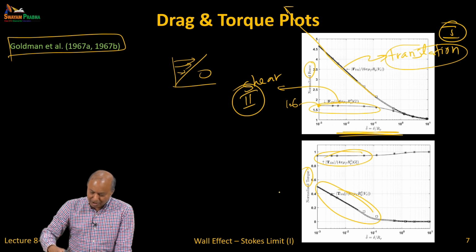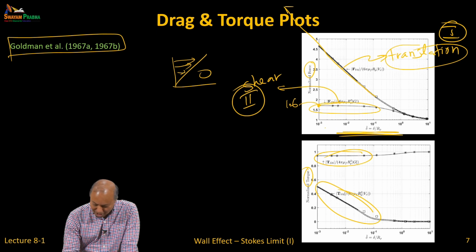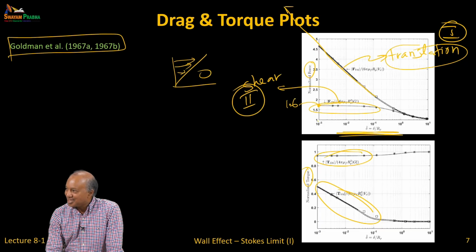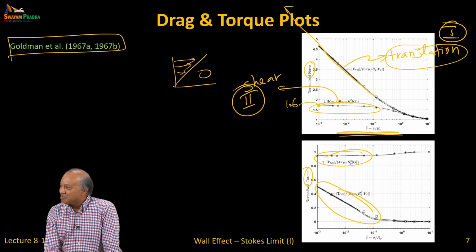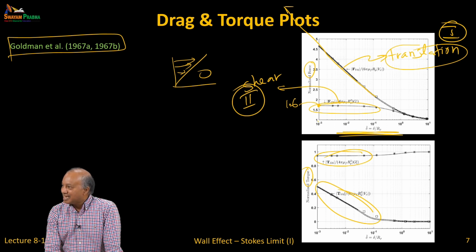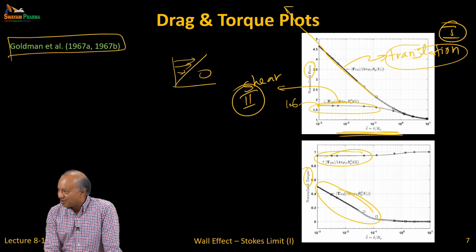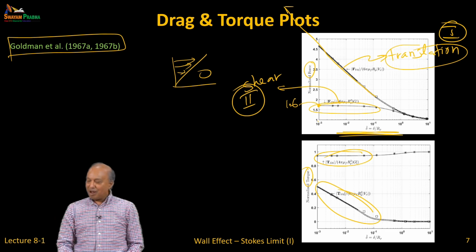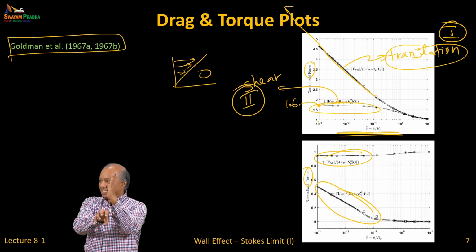So when a particle is sitting on the wall, delta is really small. Let's say 10 to the minus 7, 10 to the minus 10. Then the force will be tremendous, as you can see. Yeah, it's just a logarithmic singularity. That's why it can't slide. It will have to roll. This is for sliding. So problem 1 is particle sliding.